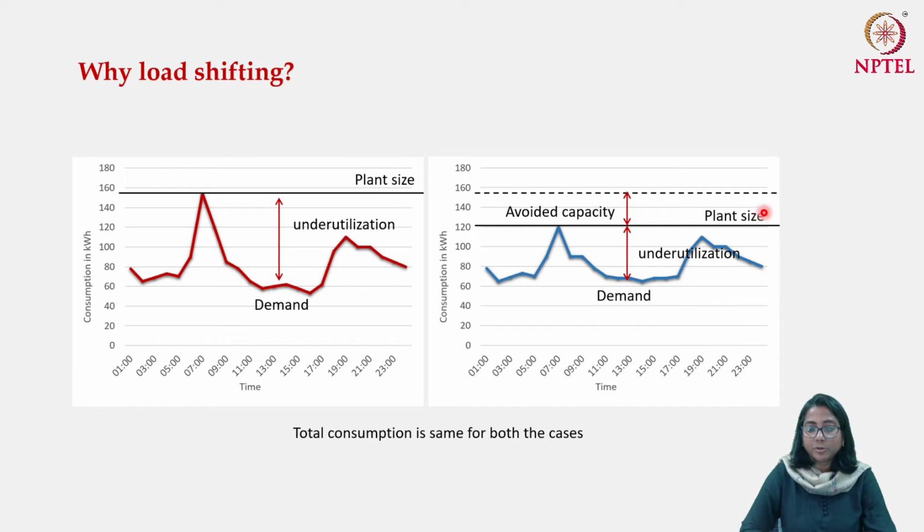During the off-peak period, if you see here, this was the amount of underutilization of the power plant. The underutilization actually comes down because of two reasons. Now your off-peak demand has gone up and your plant size has come down. As a result, there is a squeezing of this particular red line to this particular red line here, which shows a lower underutilization and the higher economic efficiency of your investment. So this is the bottom line why we want to have a flatter load curve as compared to a load curve which has very deep off-peak demand and very high and sharp peak demand.